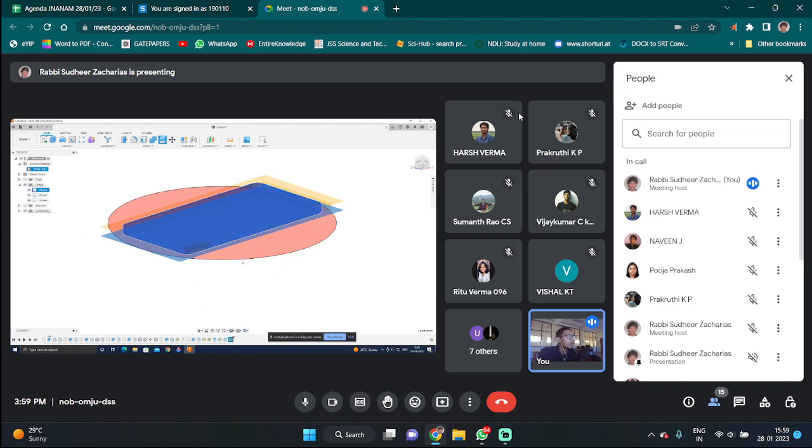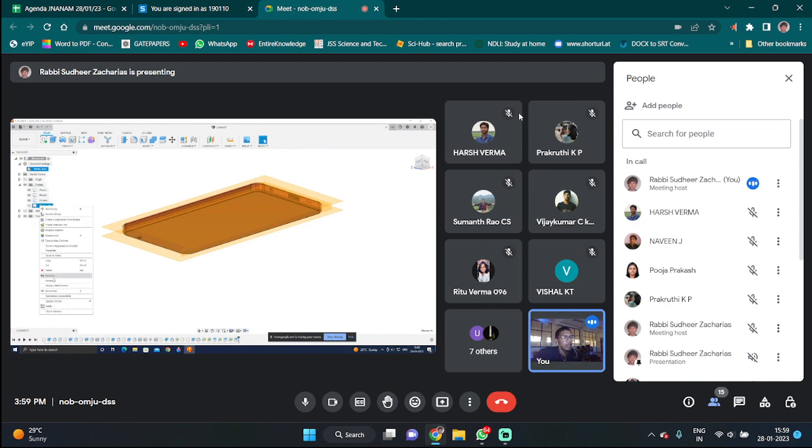So it will ask you where it is going to cut, right? On the right side also it will give you an option. It has this bar where it will tell you one body is selected, splitting to is selected. Now you can go ahead and press enter. Now we have another device created, which is the camera. We'll rename that as camera. Fine. Nice. We'll turn off the planes. Now it somewhat looks good.